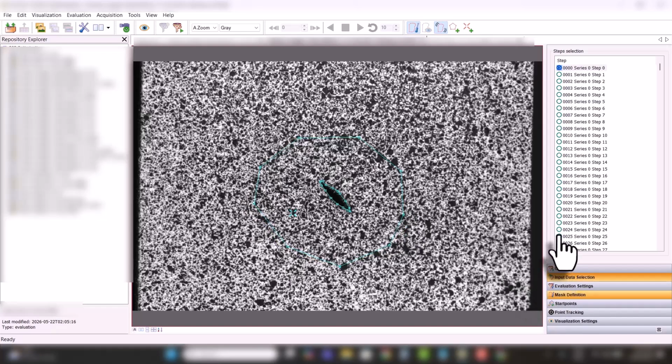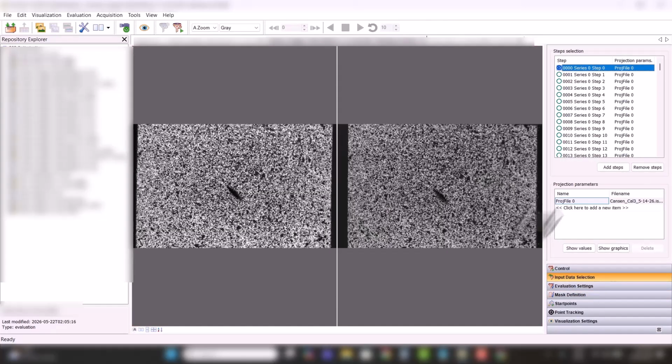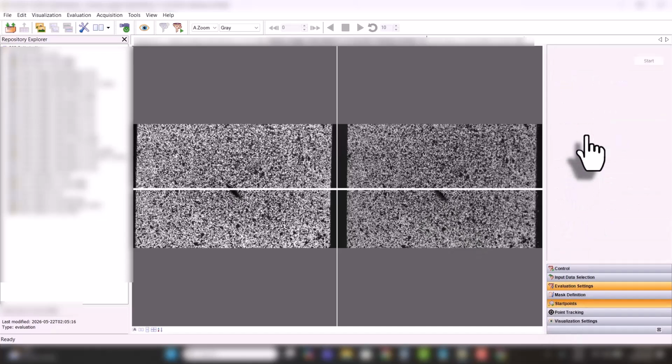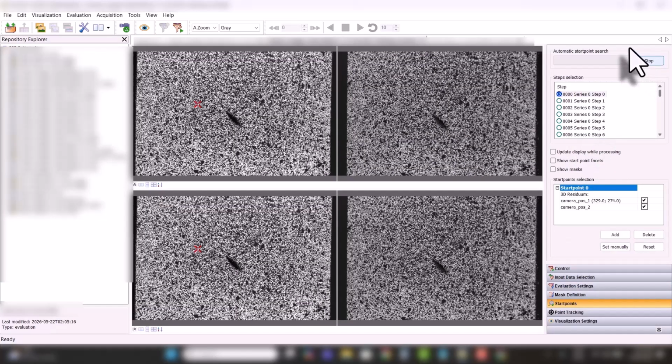Okay, now we can still use a large facet spacing just for the sake of testing this out and seeing how it works. And then for the final correlation, decrease the facet spacing. But here, we can go to 23. You can ask the ChatGPT chat you're working with to recommend a small facet size to use for the evaluation of the DIC near a notch edge. We can even try the smaller facet size after this.